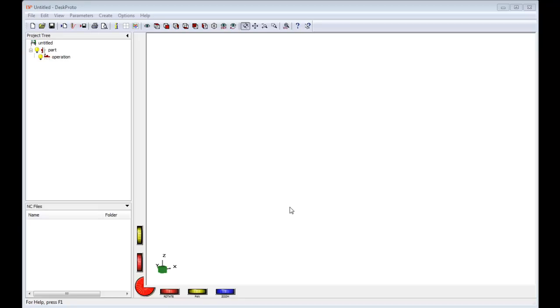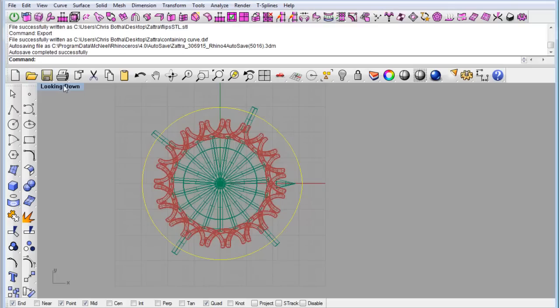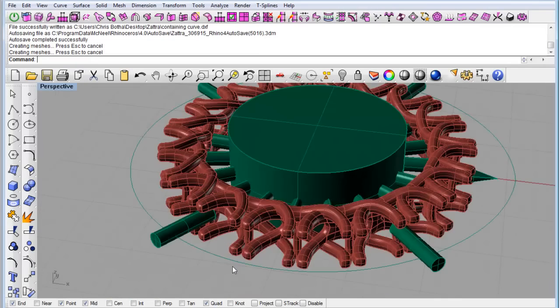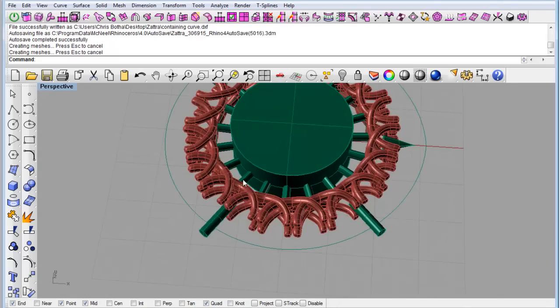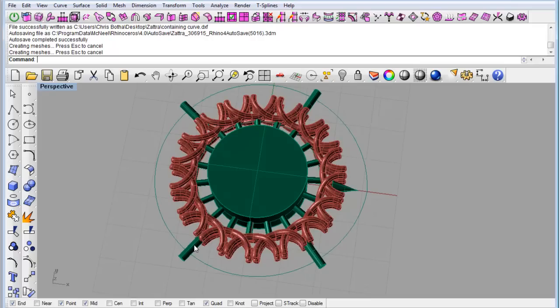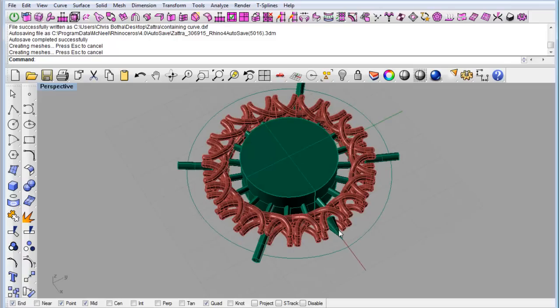Okay, so the ring that we did in Rhino, this fella that I posted, just to give everyone an idea of how that works between the CAD and getting it done on the mill, is really after you're done with your CAD, there's a few rules depending on your mill and what sort of fixturing system you're using as to what geometry needs to be added. In our case, we're adding a little pipe, a couple of supports into the hub, and an indexing cone.